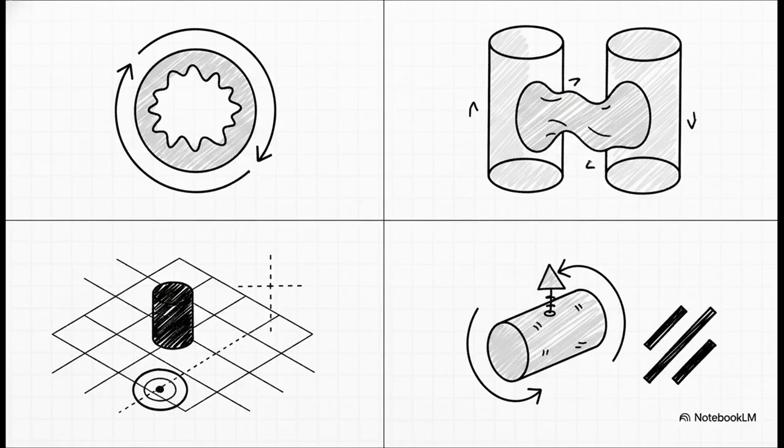Circularity, that single circle symbol, defines a 2D tolerance zone. The CMM just looks at a single cross-section and verifies all the points fall between two concentric circles. Cylindricity, on the other hand, is a full 3D measurement. The CMM actually has to scan along the entire length of the feature.